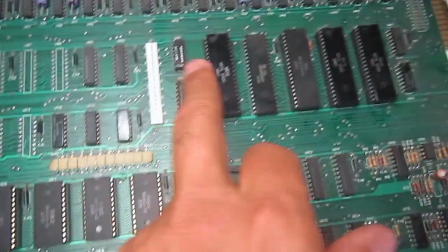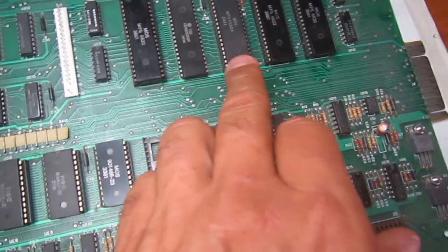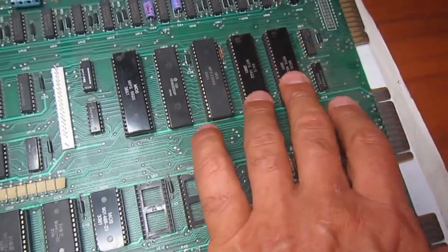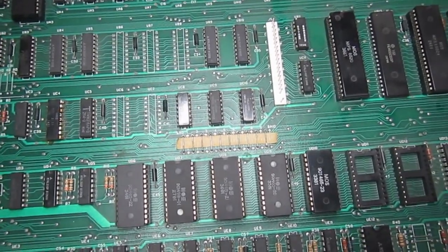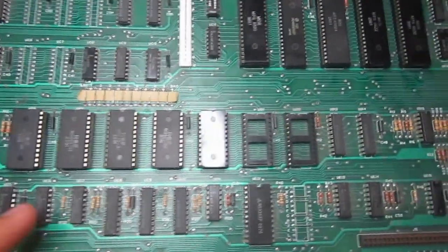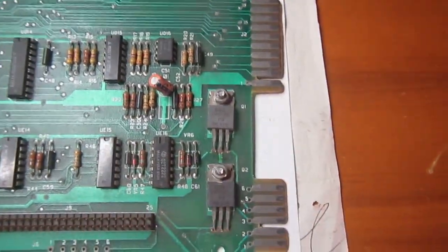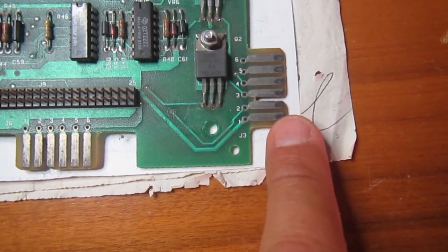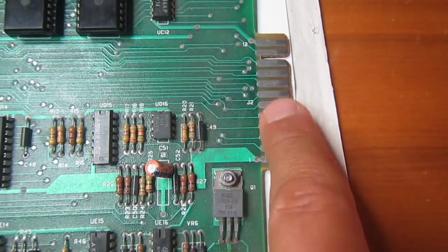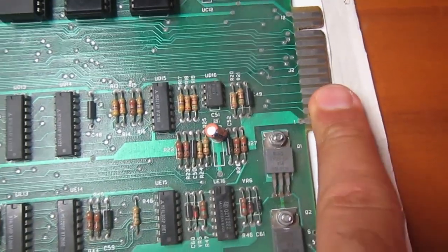Here the ROM, the major CPU, CRTC controller, 6520, 6522, all the RAM, dynamic RAM. And so let's see what we find on this board and how to repair it. Just for the record, we noticed that the interface connectors are very oxidized, so I more likely will need to retin every connector, but that would be the last step of this repair.